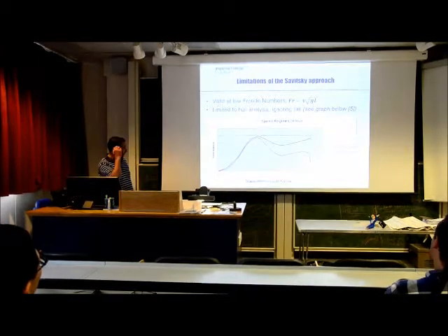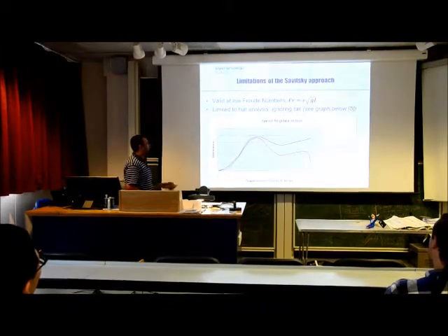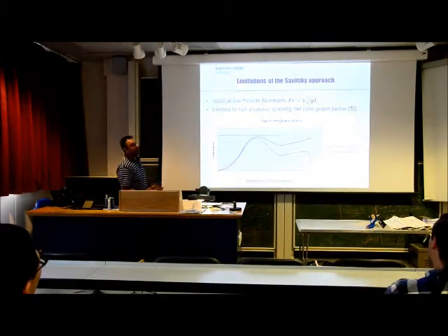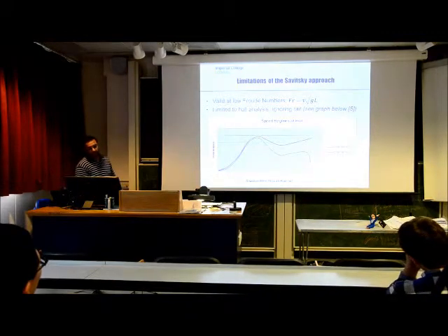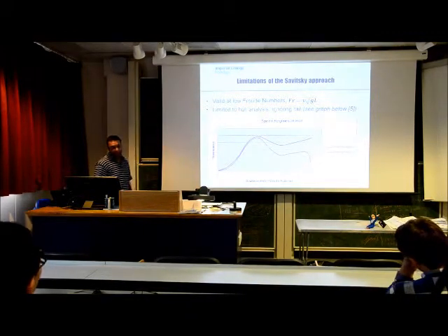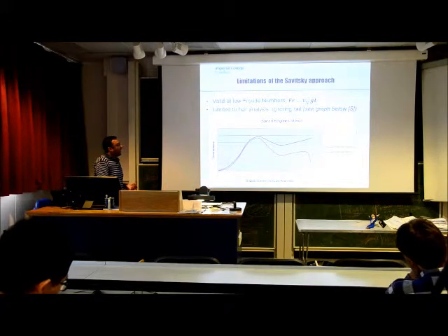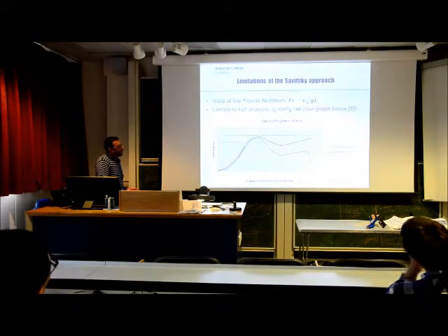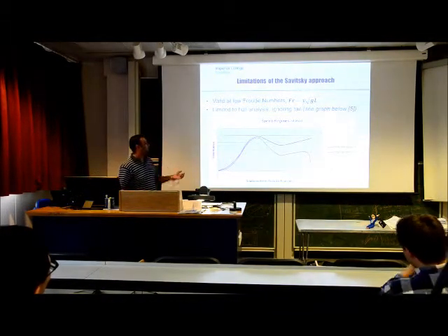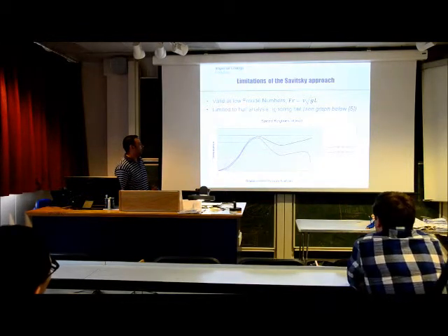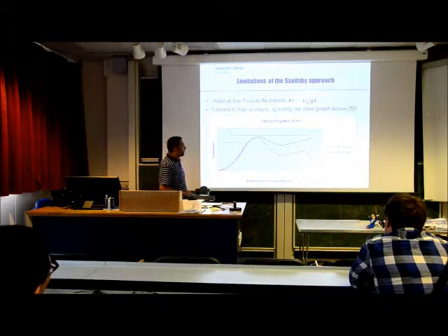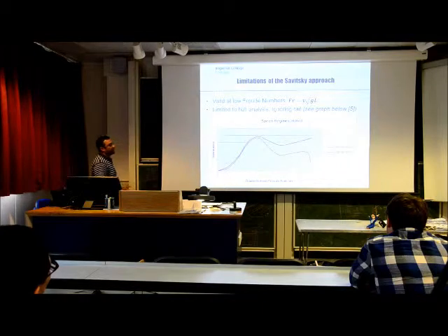And if we compare the behavior, because in the end we will look to optimize, we're looking for an optimization of the trim angle so as to minimize the drag in water. So for the variation of resistance with the displacement Froude number, basically the speed, you have a departure beyond a certain speed which occurs between a planing boat and a hydroplane, which sets somehow the limitation. So validity of the Savitsky approach is for low Froude numbers.